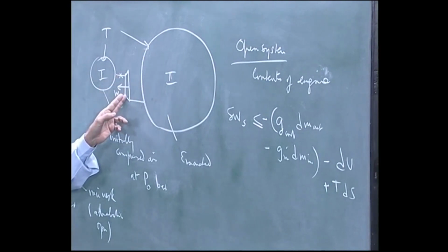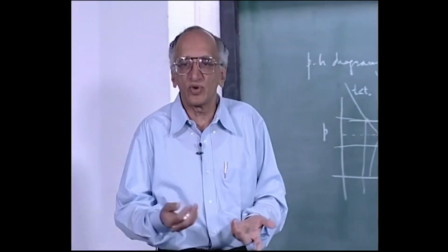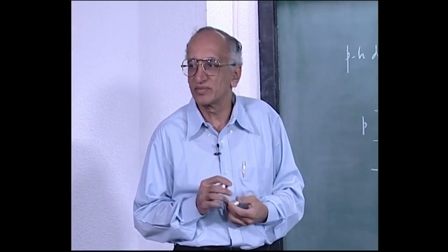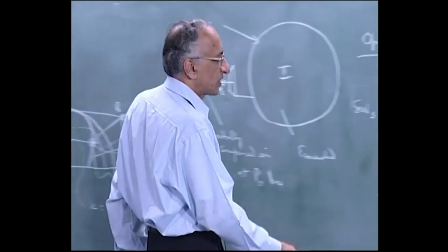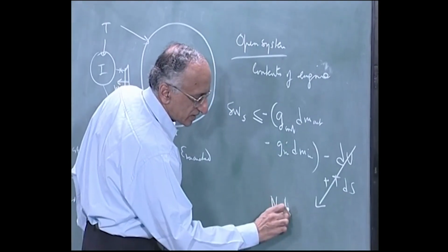So the pressure will change, so the contents will change, but the mass inside is negligibly small, therefore the internal energy is negligibly small, the change in internal energy is even smaller. Therefore we throw these two terms out, in this case not because of steady state but under conditions of negligible hold up.